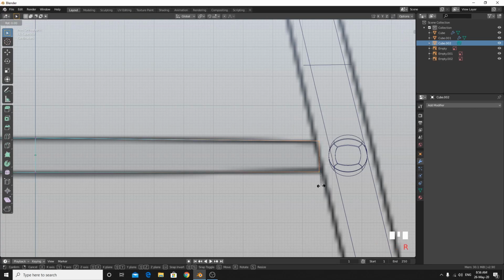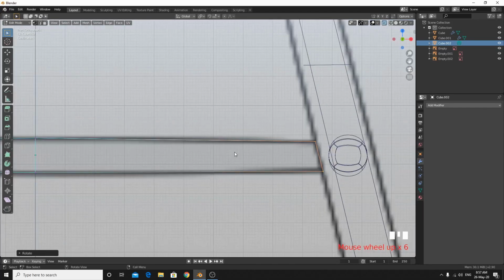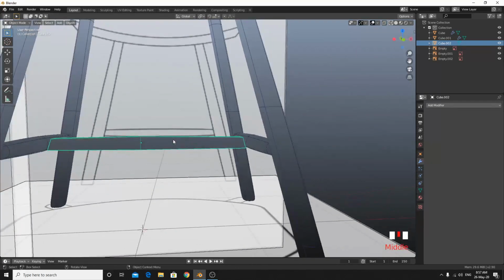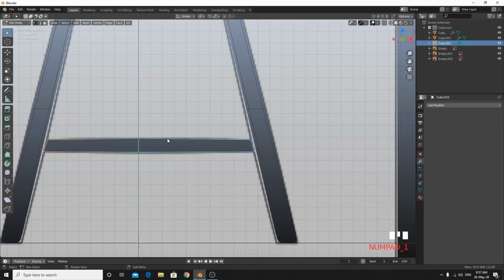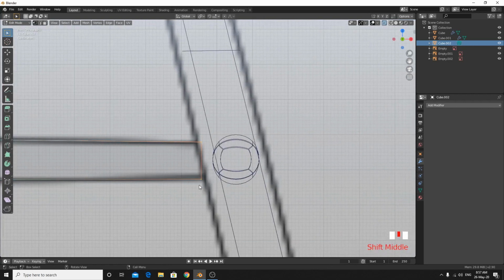So what I'm going to do, I'm going to rotate it. Wait, don't do this step. This is wrong. Don't rotate that shape, please. I'm going to show you what's going to happen. You're going to see that the shape size is getting smaller from rotating it. If I rotate more, you're going to see this problem. So don't do this step, please.